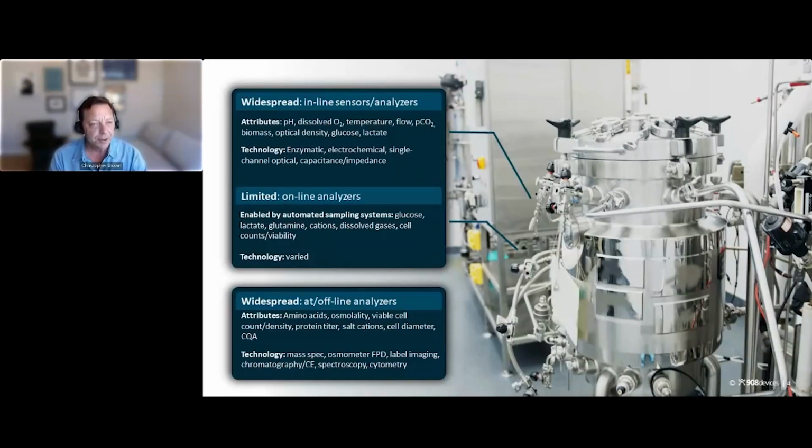There are a number of sensors that are in play in the world of process analytics, certainly in biopharma. So some are widespread, some are limited. In the widespread category of inline sensors and analyzers, a number of attributes are widely available. So pH, dissolved oxygen, temperature, flow, partial pressure of CO2, certainly glucose, lactate, optimal density, and biomass. The technologies there tend to be enzymatic, electrochemical, single channel optical, or capacitance or impedance for those attributes that I